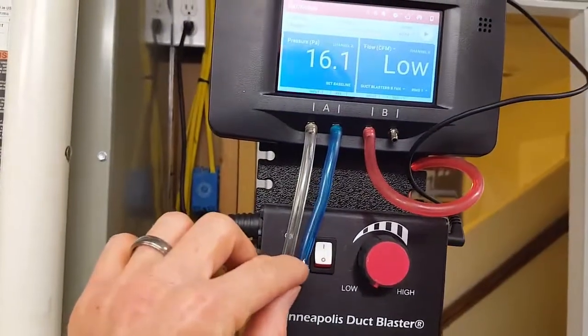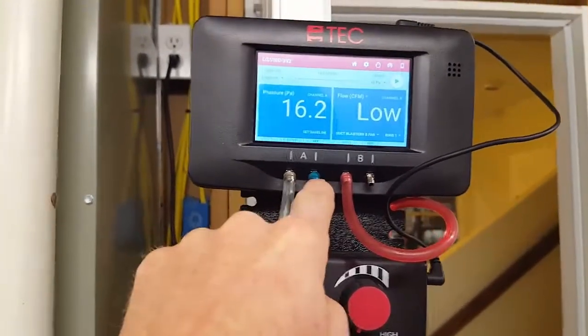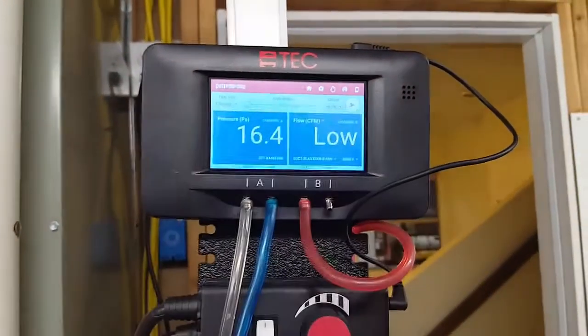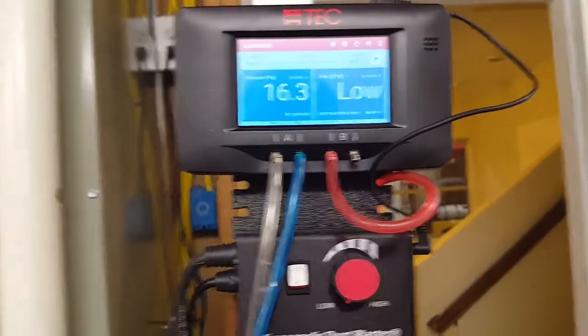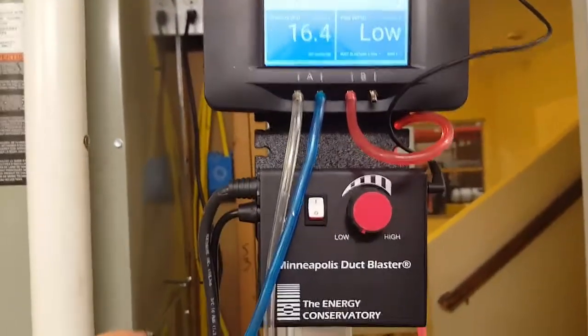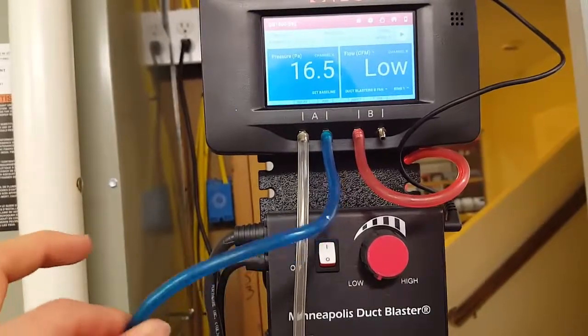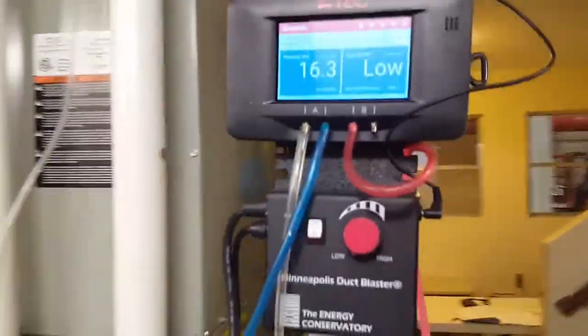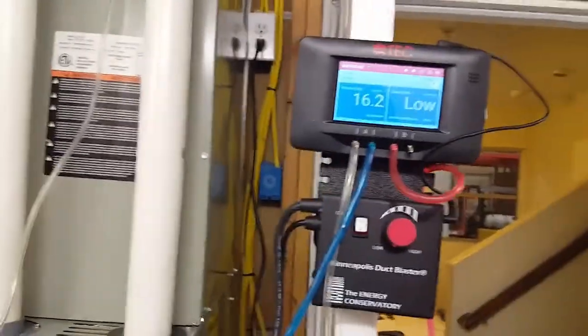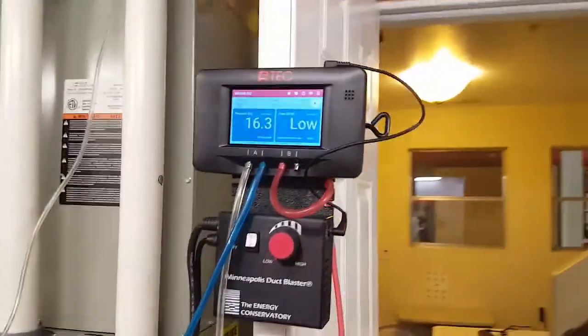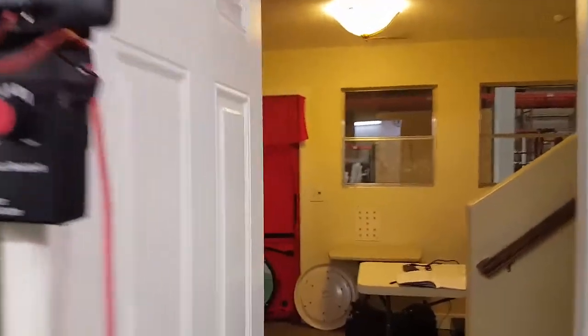But if you're used to doing this test, normally you're gonna leave this port open, and you're gonna run your fan speed to 0 Pascal of pressure, but the software that we have does not have that option. It'll only go to 25. So in order to do that, you have to reference the outside pressure. So this blue hose runs outside the building envelope. So when we run our fan, we'll actually run our fan up to 25 Pascal of pressure, which is the exact same as if we took this off and ran it to 0, and it would be referencing this inside space. So we've got everything set up properly. Now we're just going to go and run it using the iPad.